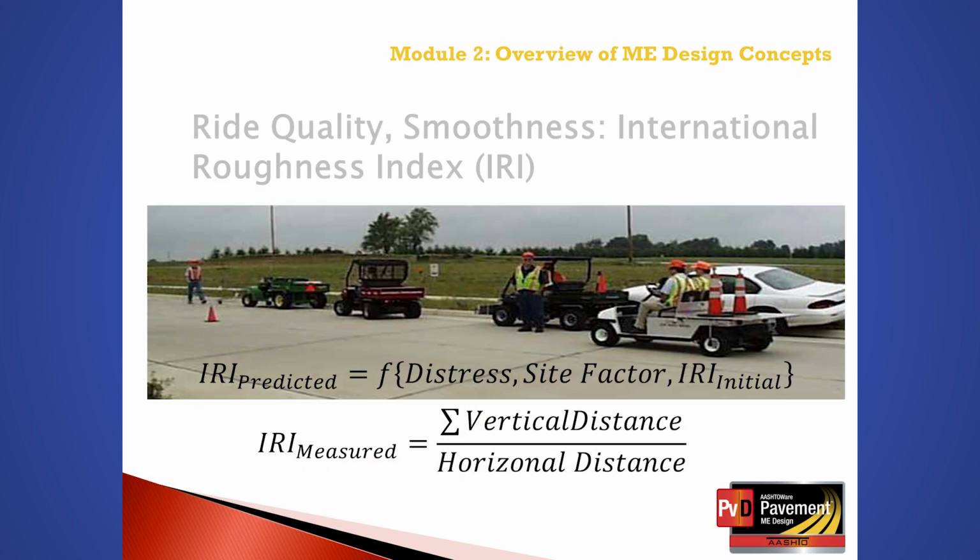Ride quality, as defined by smoothness degradation or roughness and measured by IRI, is the common performance indicator between all pavement types and overlays considered in the PMED software. It is important to incorporate and consider ride quality in design because ride quality is a major factor of concern to the user. This parameter assures the user of a smooth, comfortable ride over the pavement life.